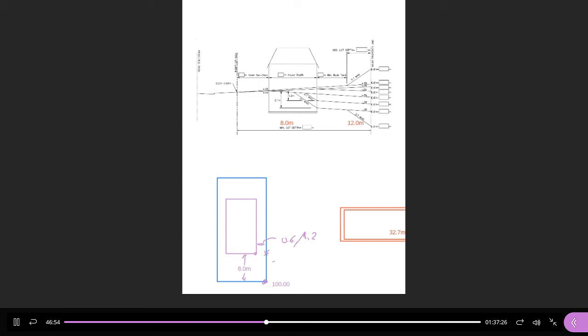Let's assume that's going to be 5%, the maximum allowed. So if the elevation here is 100, what's the elevation here going to be if we're going up at 5%? We want to drain down, so this is higher. What's the elevation at the lot line opposite the corner of the house? We're going up, yes, 100.400. That's the elevation of the lot line opposite the corner of the house.